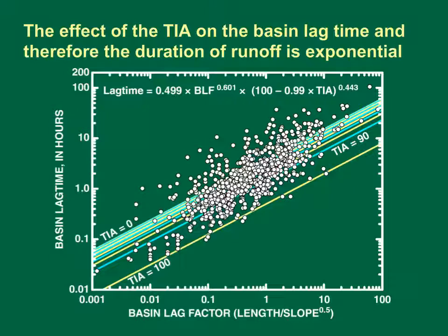The differences increase substantially as TIA exceeds about 70%. However, because most highway and urban runoff sites are relatively small, the difference in lag times are much smaller than an hour. We should try to derive the most accurate and defensible TIA estimate as possible, but the difference between adjacent TIA values probably is not critical for many small highway sites or for many upstream basins.